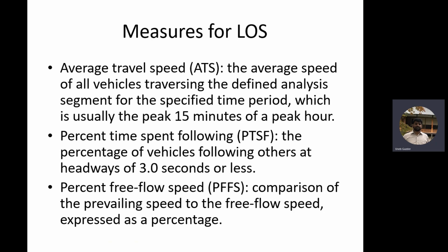Percent time spent following. Time spent following is the time during which your spacing with the car in front of you is so small that your speed depends upon it. I'm so close to the other car, I have to respond to each and every speed variation he makes. If that car slows down and I don't slow down, then there is definitely an accident. If that car stops and I don't stop immediately, there will be an accident because there is not much time or spacing between us. There is a limit here: when the time interval between you and the other car is 3 seconds or less, this is considered too short.